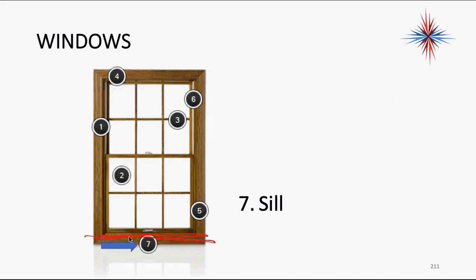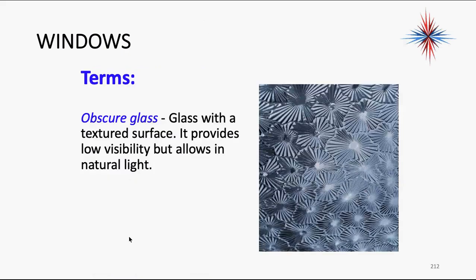All of those components we're worried about in a window, but you know what? The beauty is that the manufacturer will tell you what it is. It will give you the U value. That's why you want to use the manufacturer's information as much as possible. So do the Manual J tables I gave you.